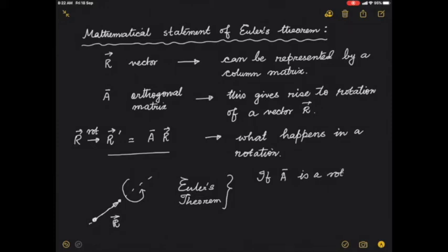if A is a rotation, right? A is a general displacement, as I said. We know that the rotation can be written this way, but any displacement can be written this way because any displacement relates the new xyz with the old xyz by a matrix. Whatever the relation is, you write it in terms of a matrix.